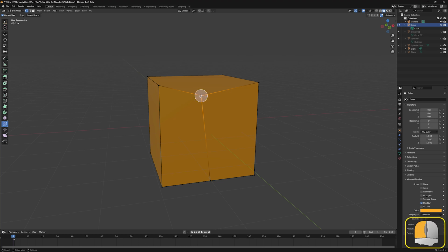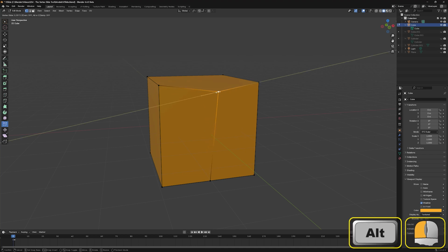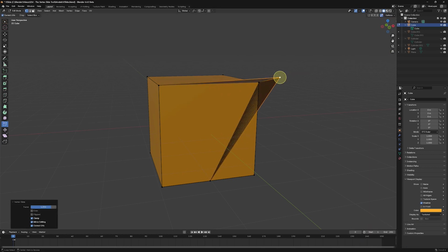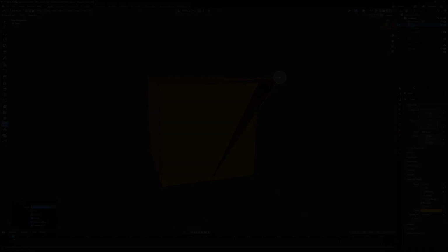As we drag the vertex, its movement is restricted to a path along any one of the edges to which it is connected. Once we've started the drag, holding down the Alt key will produce an extended tramline, showing the line along which the vertex may be dragged, allowing it to be moved beyond the boundaries of the current edge. However, it is our responsibility to ensure that we don't end up creating an invalid geometry.